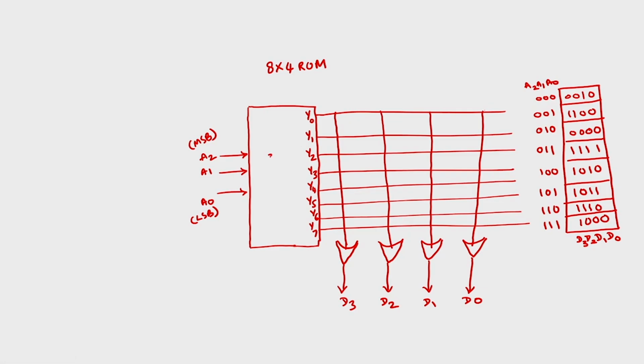Okay. This is the 3 to 8 decoder. So, if I give A2, A1, A0 as 0, 0, 0, then Y0 will be 1, and the remaining will all be zeros. If I keep all the connections intact, this will represent intact. This is the notation I am going to follow, and this cross represents blown, meaning the fuse is broken.